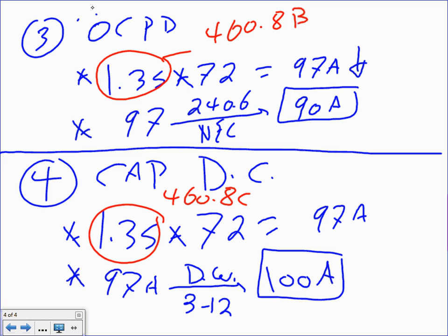And 208, if you read under the table, it says if you're using a 208 system, increase the cap size by 33%, right at the bottom of these two tables. If you're using a 208, up the size that these tables are giving you by what? By 33%. That's what we're going to do. We're going to up it by 33%.